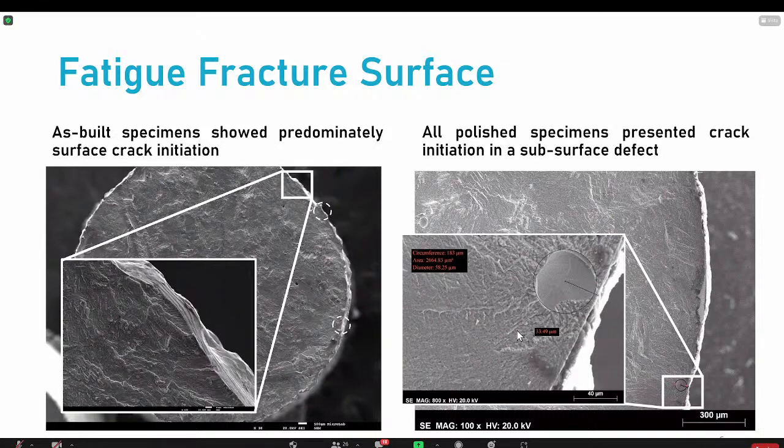Okay. Have you identified any of these defects? What kind? So mostly the most present defects are inner gas pores on the specimens and all other surfaces that we analyzed. And since it was a predominant type of defect, we did quantify the size of it. I do not have it here in this small version of the presentation. And we also have seen very few small keyholes and lack of fusions, but there were very few in comparison to the inner gas pores.